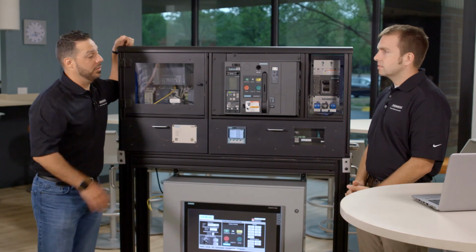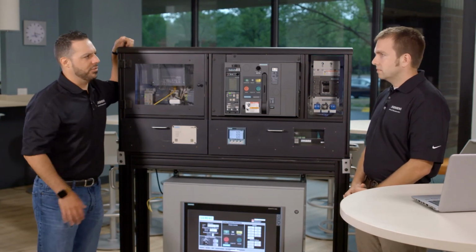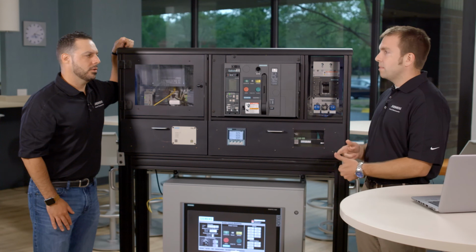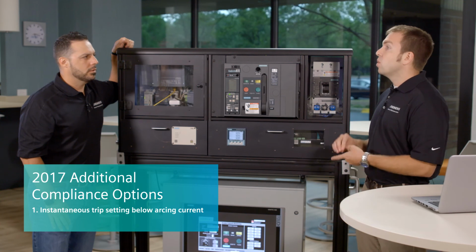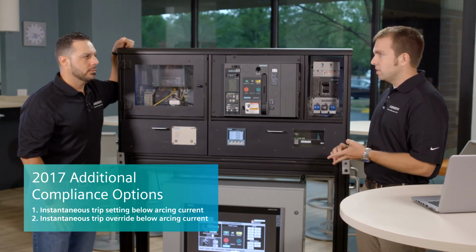So George, you just mentioned the 2014 code. We're now in 2017. Naturally, I would imagine there are some updates on those requirements. Can you shed some light on that for us? Sure. So the 2017 code kept the original 5 requirements and added 2 additional options to comply. The first was instantaneous trip setting below the arcing current. And the second new one is instantaneous trip override below the arcing current.